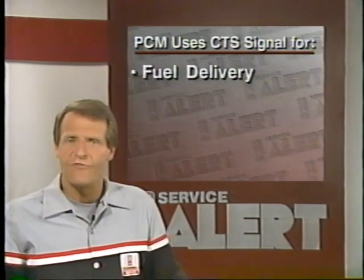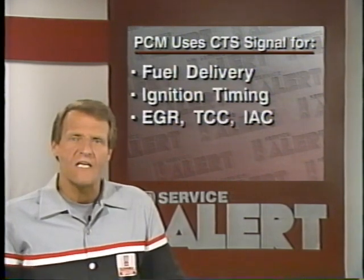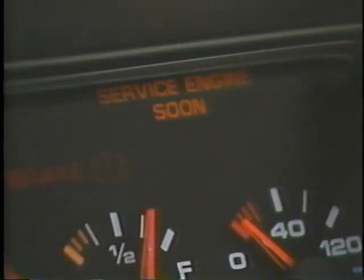The PCM uses the CTS signal to control many functions, including fuel delivery, ignition timing, EGR, TCC, and IAC operation, and cooling fan control. In addition, the PCM uses CTS output as part of its decision to run open or closed loop. When the PCM gets an out-of-range signal, it turns on the service engine soon lamp and sets a trouble code, 14 for high temperature, 15 for low.